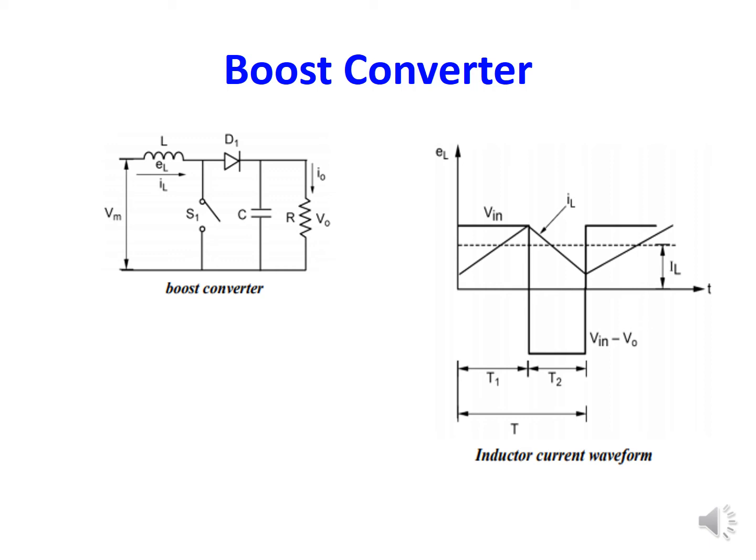When the switch is on, closed, electrical energy from the supply voltage passes through the inductor and switch and back to the supply voltage again. As a result, the switch creates a short circuit to the output. This increases the current flowing through the inductor as it has a shorter path to travel back to the supply. Meanwhile, the diode becomes reverse biased as its anode is connected to the ground via the switch.